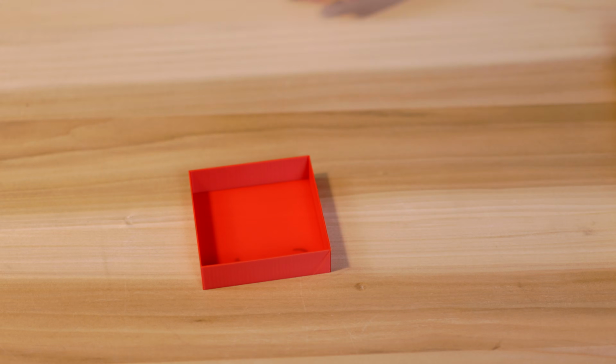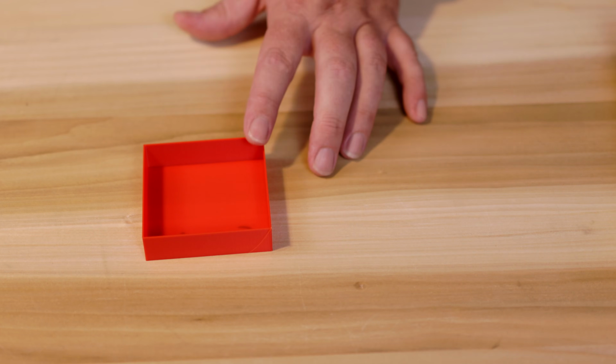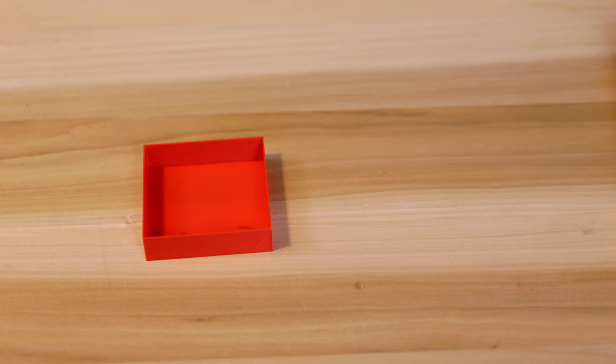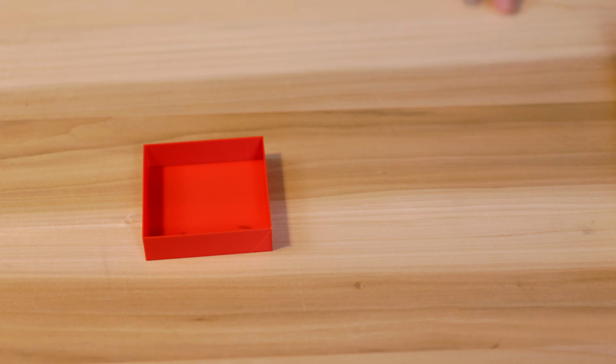As we can see, there's nothing in here. Printing tip, used for draft prints or internal prototypes. So this isn't something that I would use for a finished print, but definitely for a prototype. And it did have the fastest printing time, as you could imagine, and the least amount of material usage, as you could probably guess. And that was at 40 minutes of print time and 30.19 grams of material used if I were to print the whole cube there.